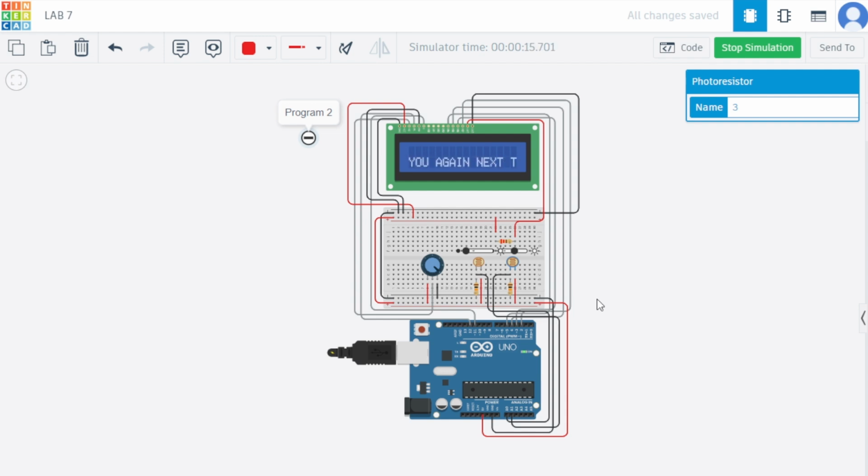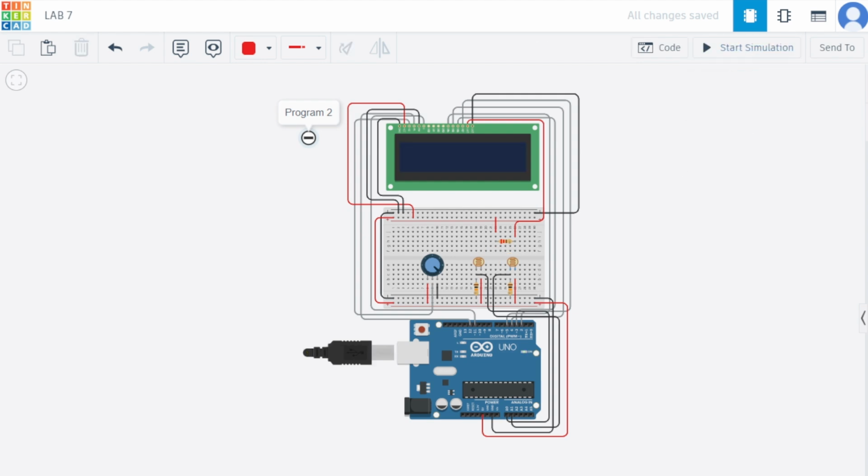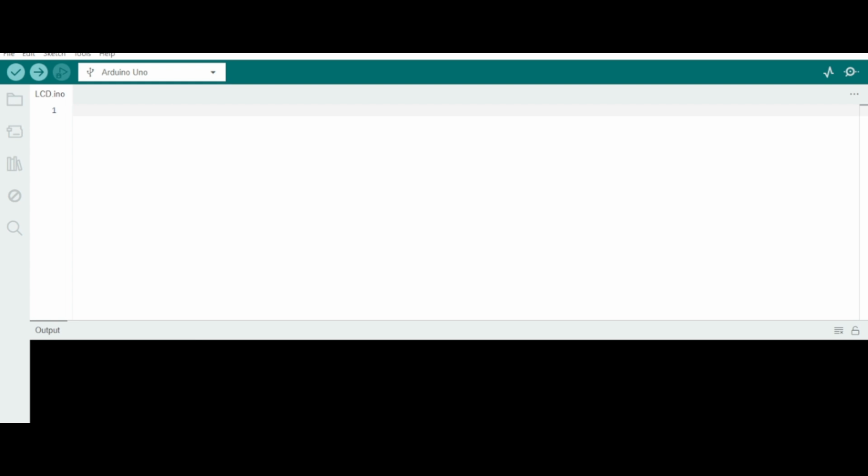To understand the code, first, the LCD is initialized and cleared. The loop continuously reads values from 2 LDRs connected to analog pins A0 and A1. A threshold of 500 determines if an LDR has sensed light. Variables are set up to store message positions and track scrolling intervals.